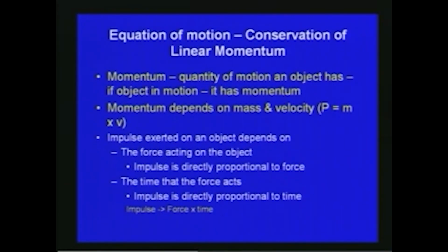As far as the fundamental principles of fluid are concerned, most of the theories are derived from them. We have already seen the conservation of mass, based upon which the continuity equation is derived, in the previous lectures. One of the other most important principles based upon which most of the fundamental laws are derived is conservation of linear momentum. So today we will derive the Euler's equation based upon this conservation of linear momentum, and then further we will derive the Bernoulli's equation based upon the Euler's equation.